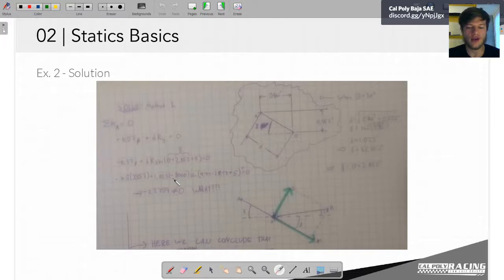If you can solve something with two equations, but then your third equation doesn't agree, often that means that the two equations you had weren't necessarily linearly independent, meaning there's more information missing that you didn't take into account. So that would mean the force might have been in the negative direction, or your sines and cosines might have happened to work out just because there are multiple solutions.